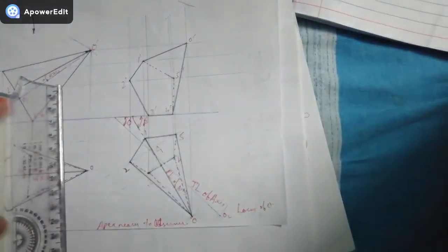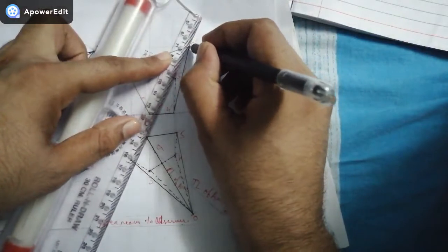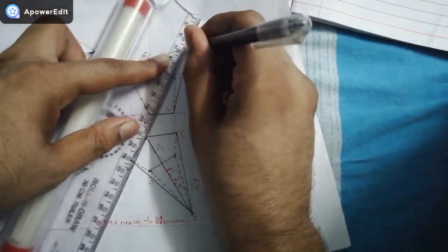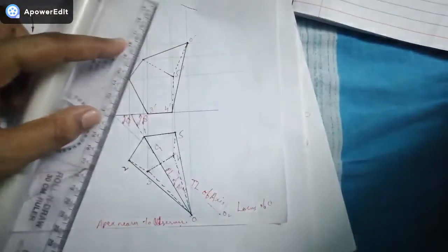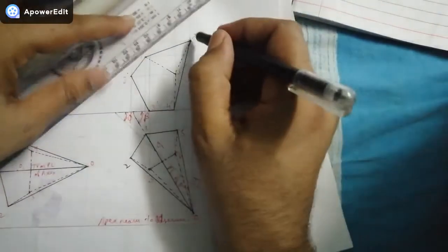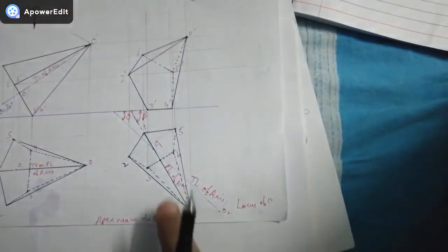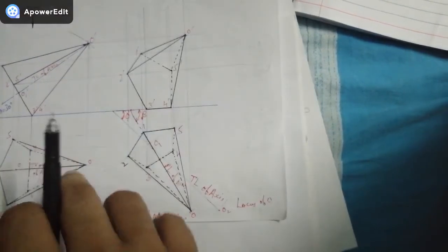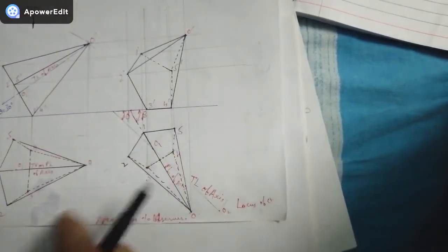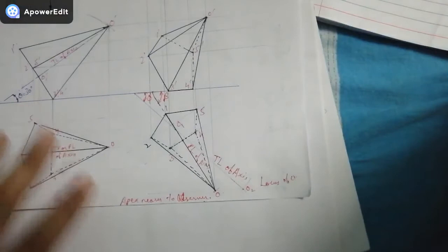Okay, now what happens about the edges? That is O to 5. Definitely, friends, you can see it is on the back side. So O dash to 5 dash will be hidden. What happens from O to 2 and O to 3? O to 2, of course, if you can see, it is there in the front, it will be dark. So friends, O to 3 from the top is hidden, but because it comes in the front side, the edge O to 3 will definitely be visible, and this completes the front view, finishing front view.